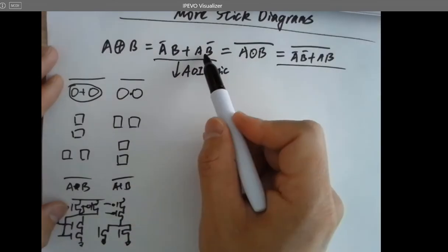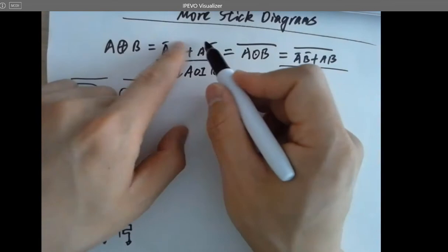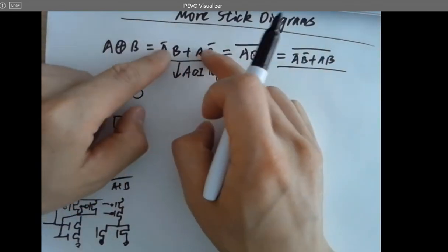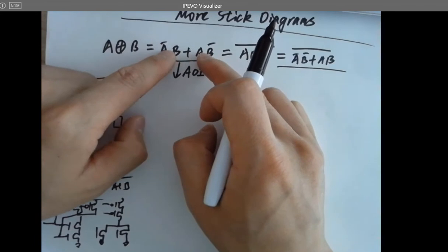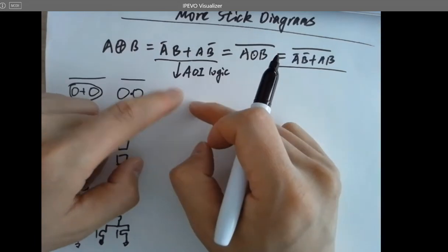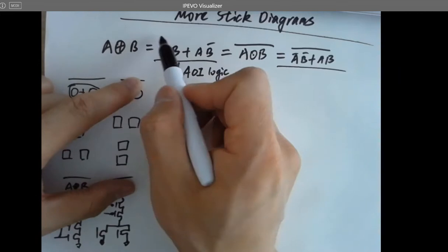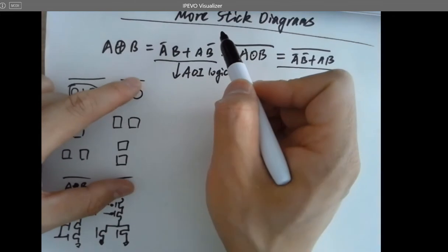And also for this one. But for these two blocks, it's an OR logic. So you want to have these two blocks in series for the PMOSes and in parallel for the NMOSes at the bottom. And then eventually invert it. So you don't have to get two bars on the top.